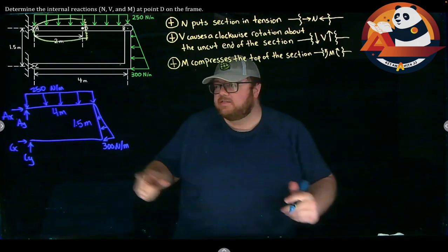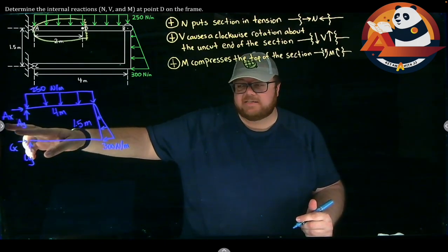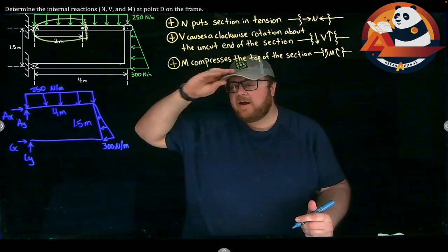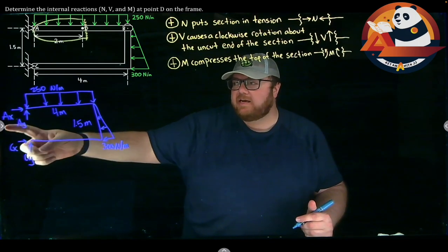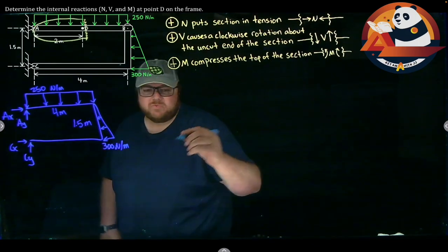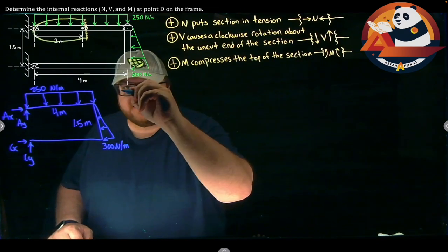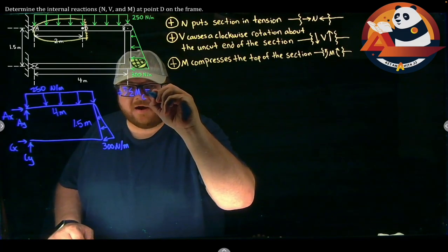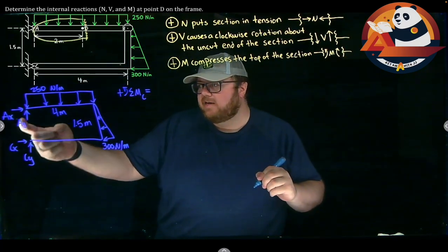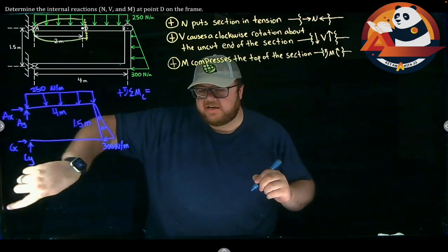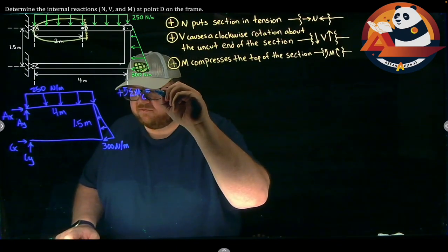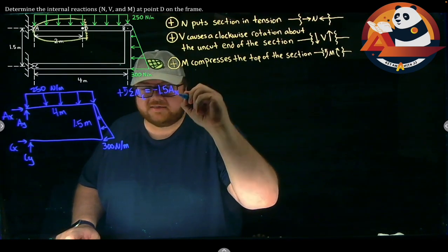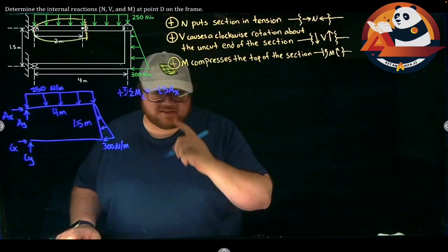All I'm looking for on this, I want to find AX and AY. AY would pass through C. There's no way I can find this with the overall free body diagram. I could come in though and sum moments about point C, and I get AX out from that. So let's start there, with positive going counterclockwise. Let's sum up our moments about point C. If I'm doing that, I'm going to get a clockwise rotation from AX. So negative 1.5 AX. Force is AX, distance is 1.5.